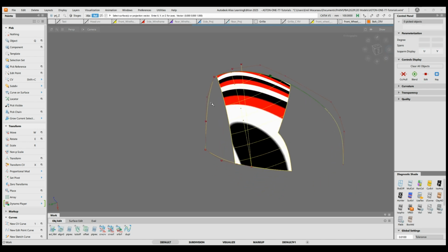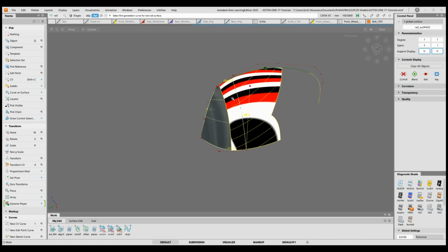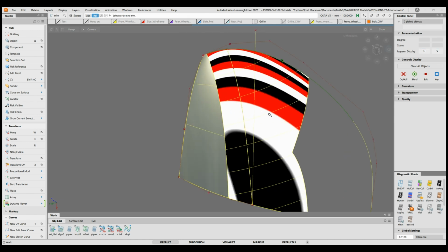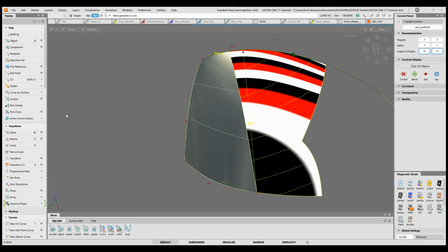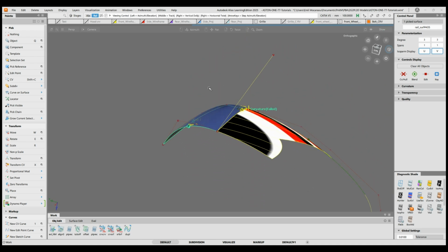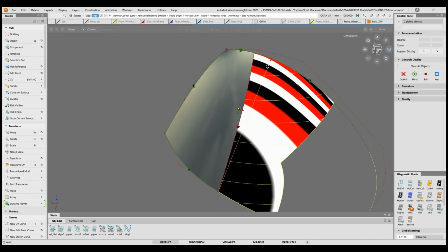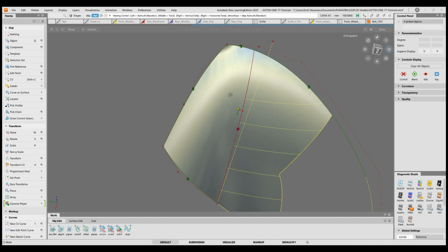So now we're going to build a monorail, that curve, that one, this one, and that curved surface. And let's go curvature on both sides, explicit control. The rail will be degree 5. That should do for the moment.